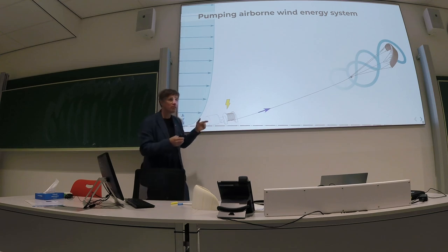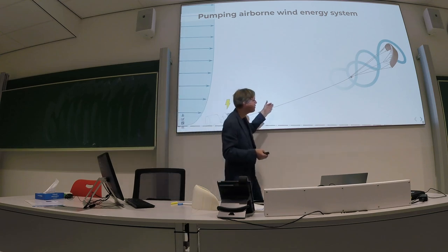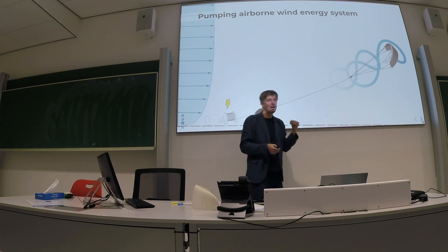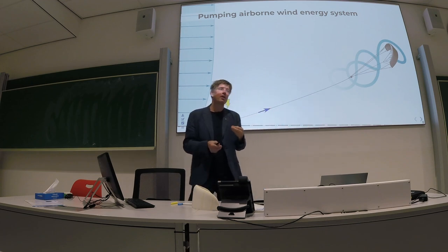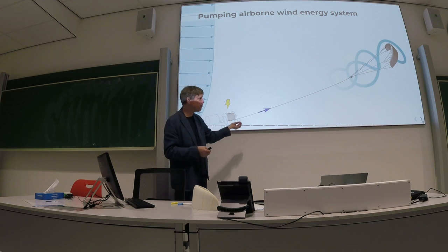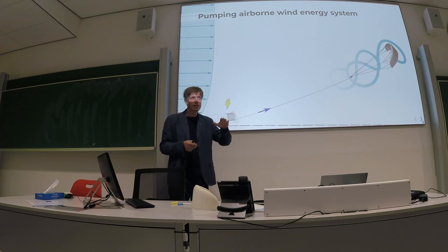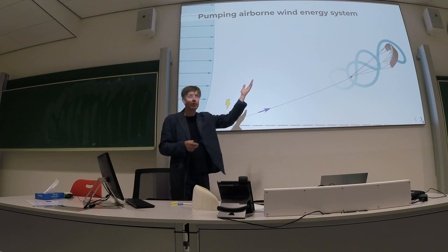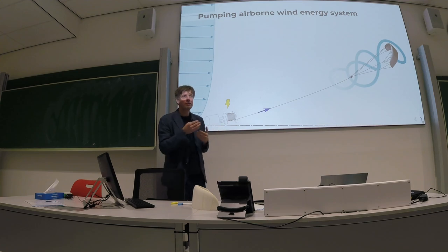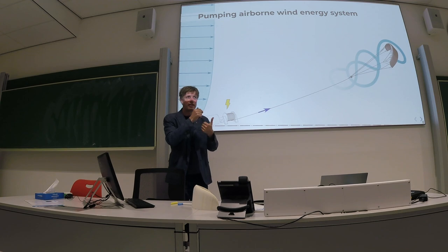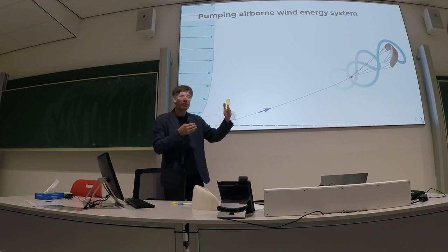And as was asked earlier, the longer the tether gets, the higher the drag will become, the higher the impact on the performance. On the other hand, flying higher sometimes gives you more wind speed because the wind speed increases with height. So this is really a trade-off problem where you need to look at the instantaneous wind profile and how much tether you have.